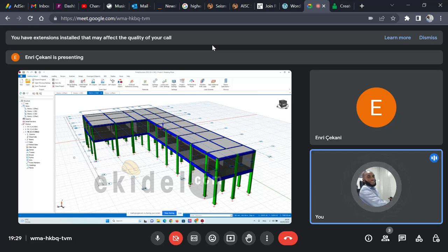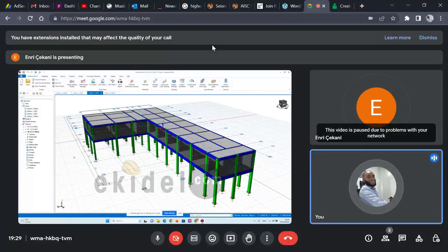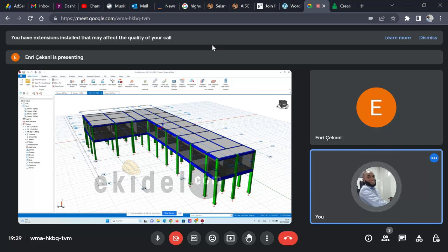Then there is also the last one, which is not mostly used, which is the mechanical way of doing the hoops, like a link, but that one is not mainly used. But the first five which I said, which are the link spacing, the link bar diameter, the link and bar steel strength, the shape of the link, and the arrangement of the vertical bars, these are the major factors that contribute to a stronger confinement.